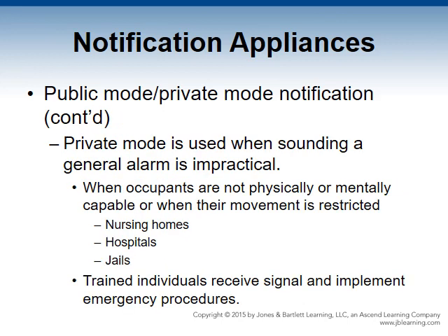A private mode notification is used when sounding a general alarm is impractical. It is appropriate when occupants are not physically or mentally capable, or when their movement is restricted, such as nursing homes, hospitals, and jails. Trained individuals receive the signal and then implement appropriate emergency procedures.